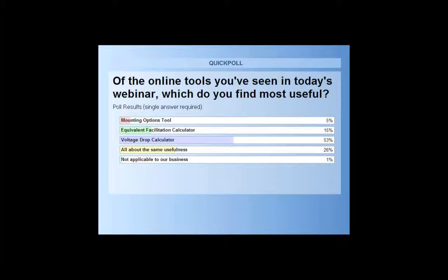So if you look at the calculator, it's simply asking you the candela of the strobe you're using, the size of the room in square feet, and then the height of the ceiling. All of those things together then provide you the calculation showing you are meeting the light output requirements per NFPA. And so really a lot of people now are using that calculator for strange applications, installations where you have an odd ceiling height.